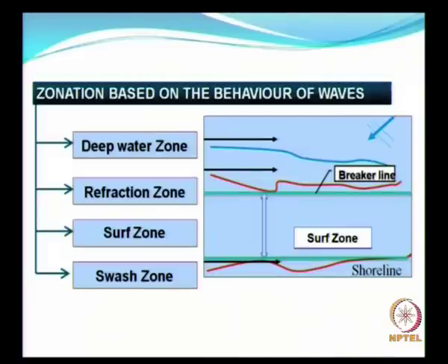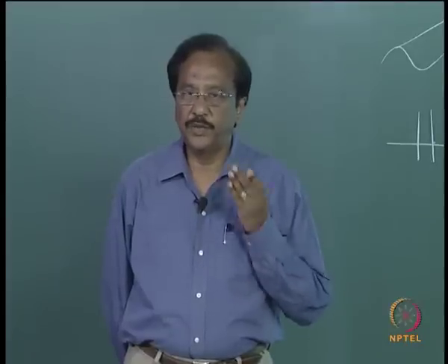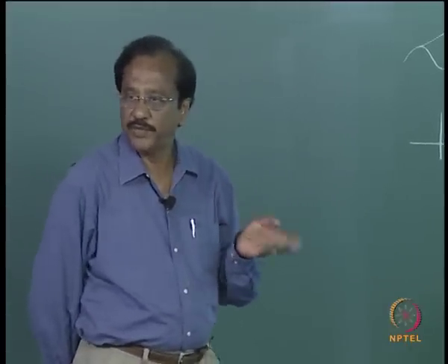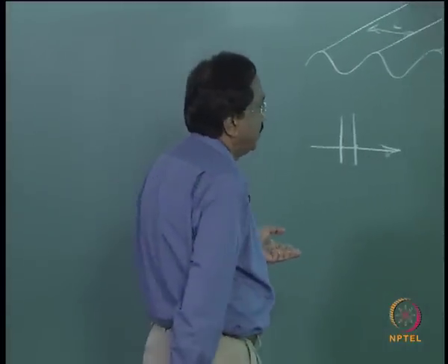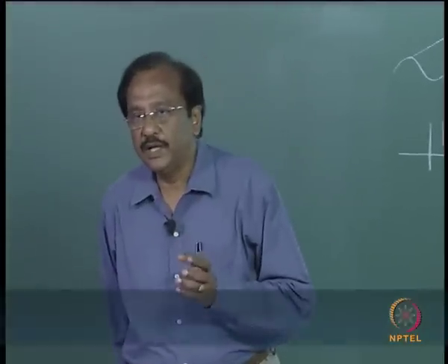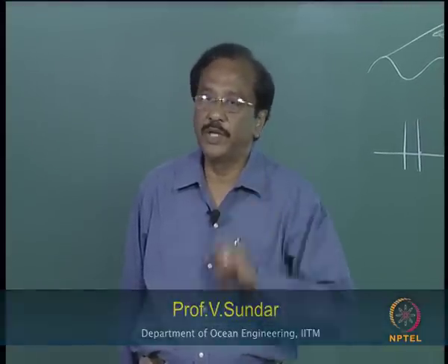Why are they parallel to each other? Because the speed with which the waves are moving in deep water is not a function of water depth. So, you have a very well defined direction when the waves are moving in deep waters.